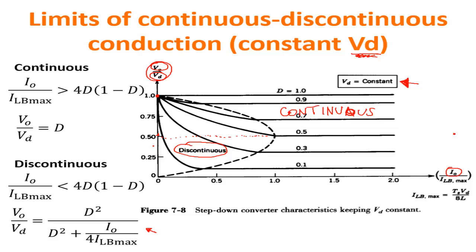All these components are typically integrated except for the inductor. Inductors are, as of now, difficult to integrate, especially the large inductors that you need for these DC-DC regulators, and therefore they are off chip. So you need to accommodate on the board one chip for the DC-DC regulator plus one inductor, because you cannot integrate it.